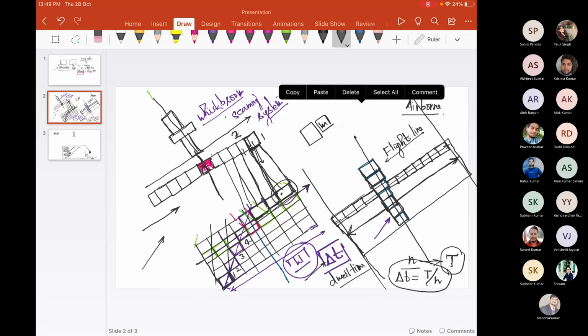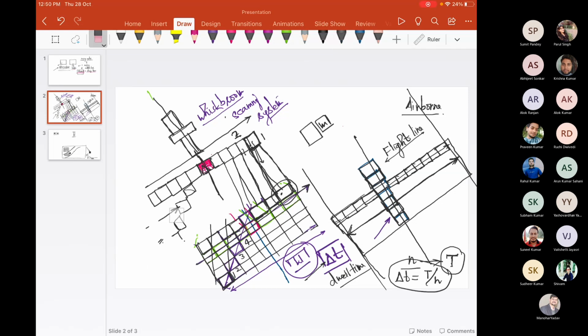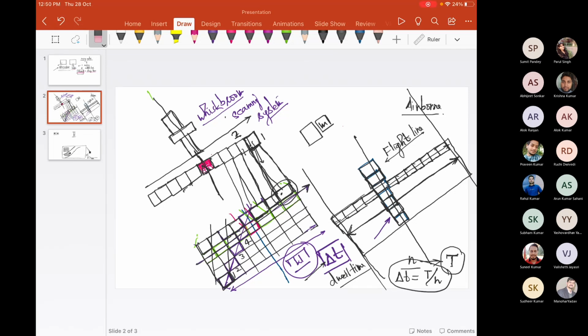Here you can notice that GRCs are acquired in a slant direction, not perfectly perpendicular to the flight line, while in this case, ground resolution cells are acquired across the flight line. While in the first case, the direction is not completely perpendicular, it is slant, somewhat tilted from the perpendicular direction of the flight line.